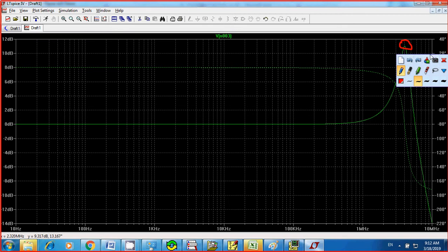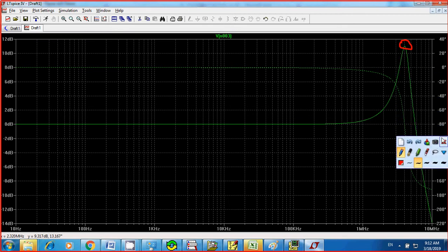And you know that for cut low and cut high, what you can do is that this is the peak of your frequency response, and you go down by 3 dB, right? That's going to give you, on the left, the cut low frequency, and on the right you drop down by 3 dB. That's going to give you the cut high, right? And the difference between the cut high frequency and the cut low frequency is the bandwidth.